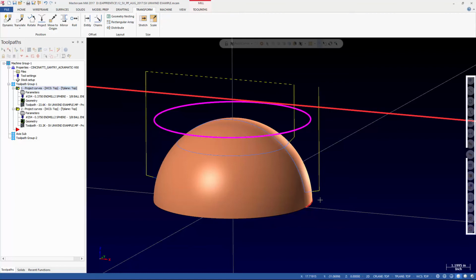So if you've got a 4-axis vertical program that uses an A rotary and you want to translate it to a horizontal machining center, you can just move the part from one machining center to the other, and using the kinematics of the machine and the envelopes of interference when it rotates the parts and the fixtures, it will automatically reprogram all of the retract and approach motion for you.